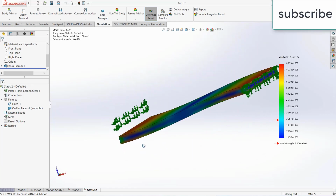A question arises: what is the advantage and where are these kind of things used? Suppose you have a beam, you know that your beam is going to deflect by 3 mm and you want to calculate how much stress is generated due to that displacement. At that point, you use advanced fixtures. There are many other instances as well, for example vibrations, where you know the amplitude at which it is going to vibrate. You can also use it there to calculate the stress. Remember, these kind of advanced fixtures are mostly used for stress and strain calculations.